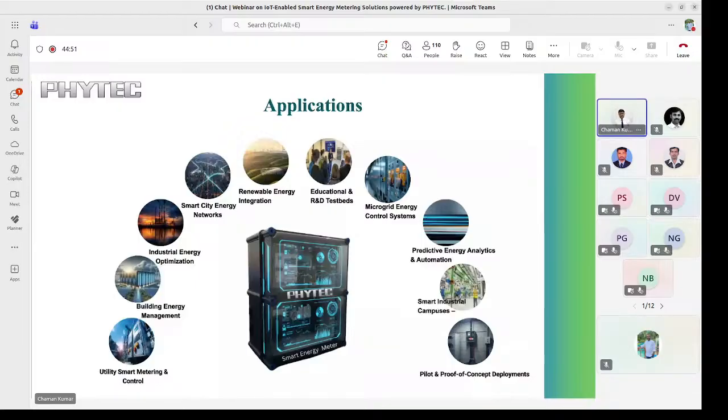Now after that, we go to the data link layer. In the data link layer, we need to understand HDLC, which is basically High-level Data Link Control. If I want to read data from, say, the optical meter reader or RS485, then we use this HDLC header. In that HDLC frame, we have an envelope, a header, and the OBIS code also.